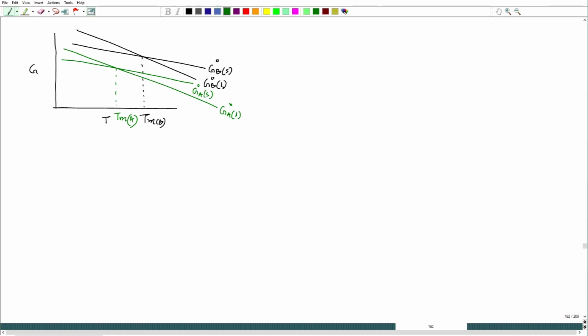So, this will be my reference free energy for solid and liquid A and B, and here we are taking the B melting point to be more than A. The placement of those lines is arbitrary, remember; these particular lines are placed as per the Cp values of solid as well as liquid B, and the solid and liquid Cp values of A. If we take experimental values, these positions can also change. They can crisscross each other depending on the values of Cp's.